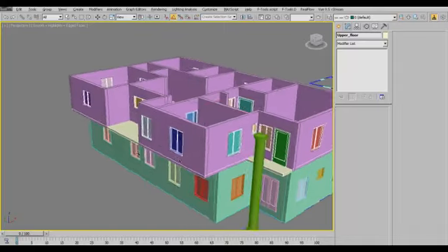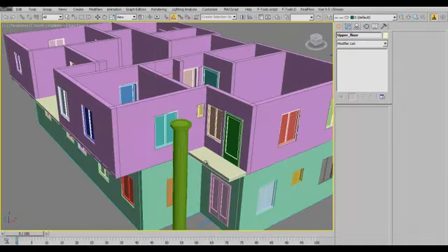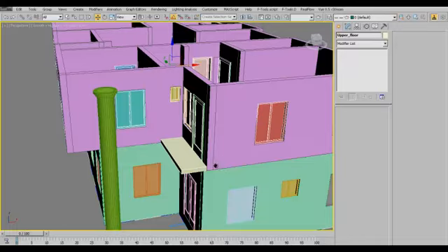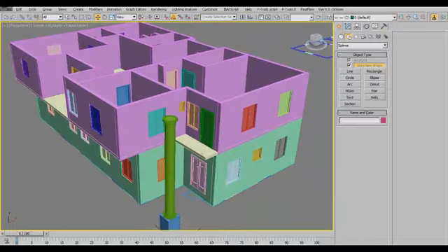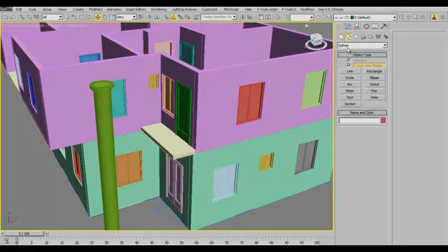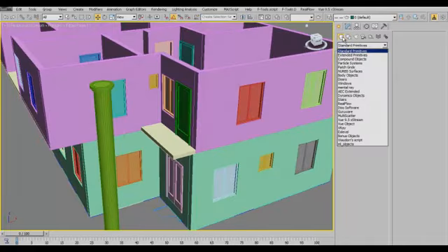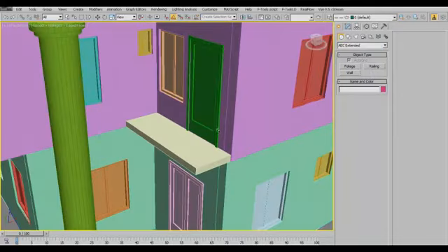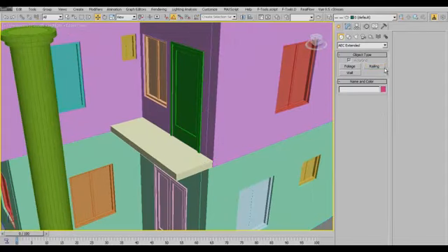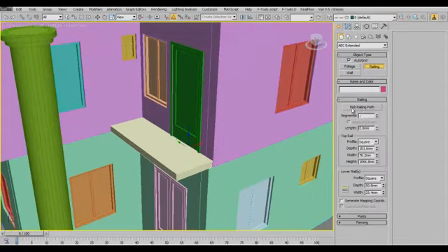So what we're going to do now is create a railing, and railings too are AEC objects, so it can be done from create geometry, and we come to AEC, which we saw initially when we were trying to create our walls. So right now we could as well just pick our railing and create, but before we create our railing, we'll have to set a railing path where we want it to be created.